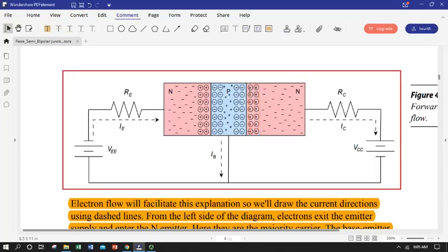So what actually happens is the electrons that we originally pushed out of the negative end of our battery came across the emitter. We pushed up the hill emitter base. They scooted across the base without getting recombined or flowing back out, and they got accelerated. They flowed down gradient into the collector, and then of course are accelerated across the collector because it's attached to the positive terminal over here.